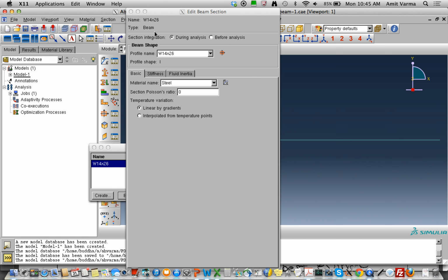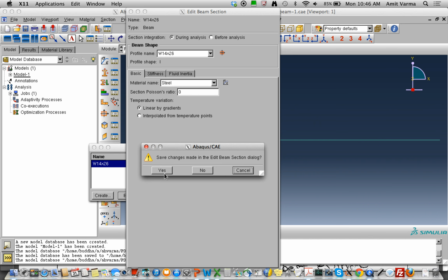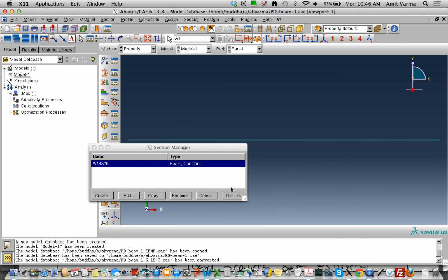The problem with that is it is not going to be as accurate when the axial forces change or when the loading changes. So right now I have axial force equal to 0. So whether I do it during or after analysis, it won't make a difference. But when I have axial force introduced, I probably want to stick with during analysis. And that's why it's been introduced like that. So that's the big thing, is defining the cross-section.